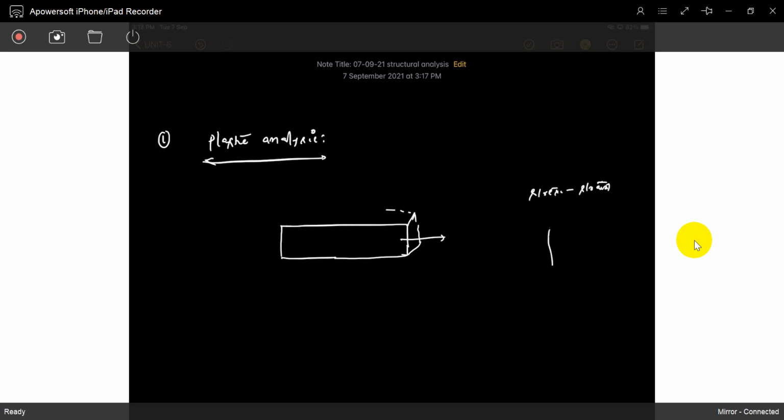Stress strain curve of anything, be it concrete, steel, anything. So how much can you apply? We can apply up to the failure point, but we will take only up to the yield point, with a factor of safety on the yield point. So based on that, what is the yield stress? The yield stress is denoted by Fy.